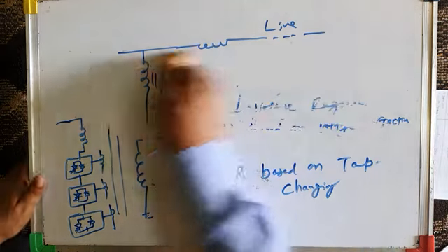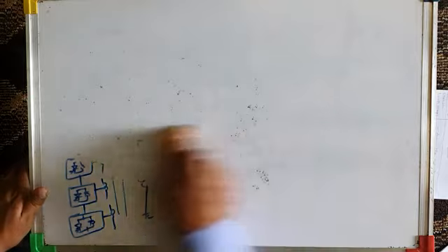So that is all about various types of FACTS controllers. Summarizing, I have discussed with you these series FACTS controllers. And I told you that a series FACTS controller basically provides or produces a variable impedance or variable inductance or variable capacitance or variable power source in series with the line. Fundamentally, series controllers actually inject a voltage in series with the line.